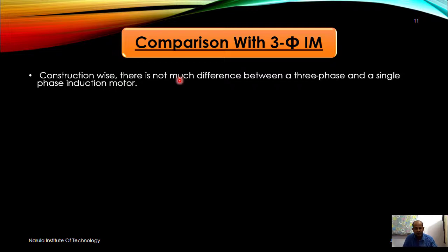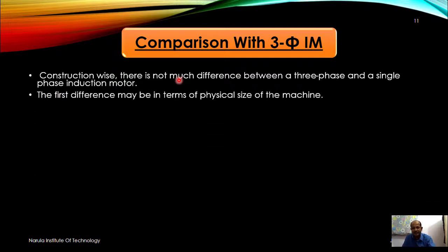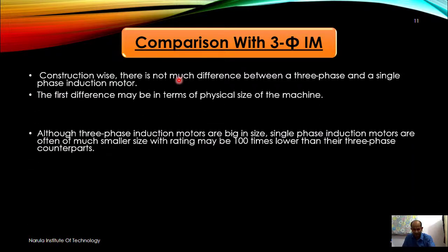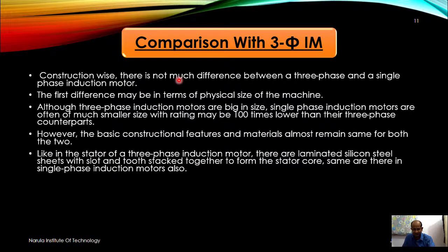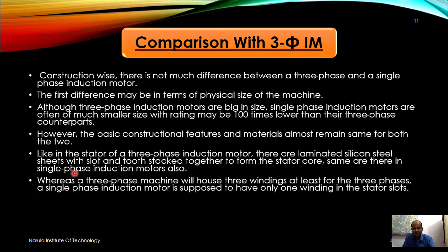So this is the same case here, right? The stator of a three-phase induction motor is laminated, as I have mentioned, and the slots and teeth stacked together, which form the stator core, are made of silicon steel.